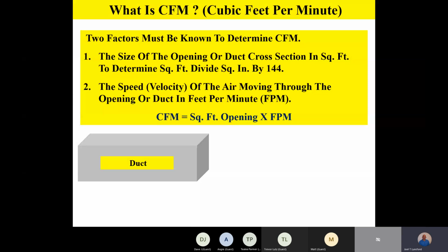in those windows. And once you do that, it'll start giving you information in different parts of the calculator as far as duct sizing and equivalent sizes for rectangular duct. And there's all kinds of stuff, but these duct calculators are designed to give us important information when we're designing a duct system. And the first window I always like to talk about is velocity in feet per minute at any given CFM, because that goes hand in hand with what we talked about earlier in module 1, that there's always going to be a velocity and a CFM relationship.